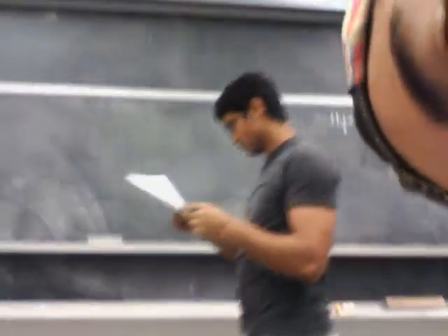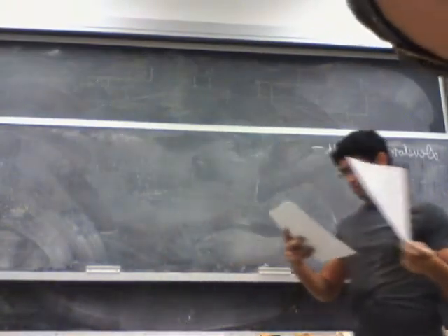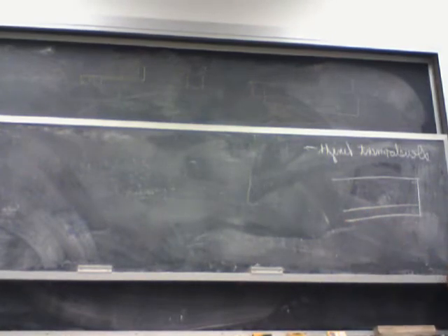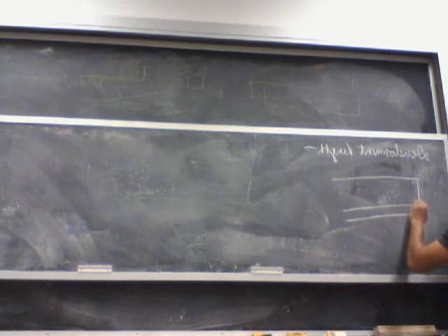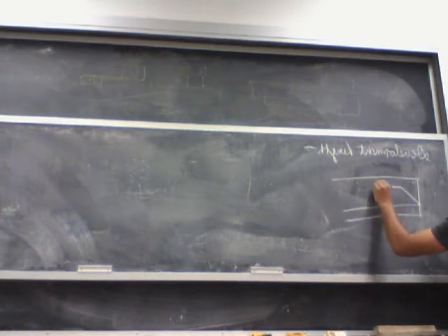All right. Okay, so the next thing is the development length. So in development length, what it simply is saying is that if I have a concrete cross section and if I provide a pre-stressing strand, the entire length of the strand doesn't actually have the same pre-stressing force, because since the force in the strand is only able to occur because it's bonded to the concrete, what actually happens is the stress in the strand actually increases from 0 to a value of FPS within a certain length of LD, and then it has a constant value of FPS.